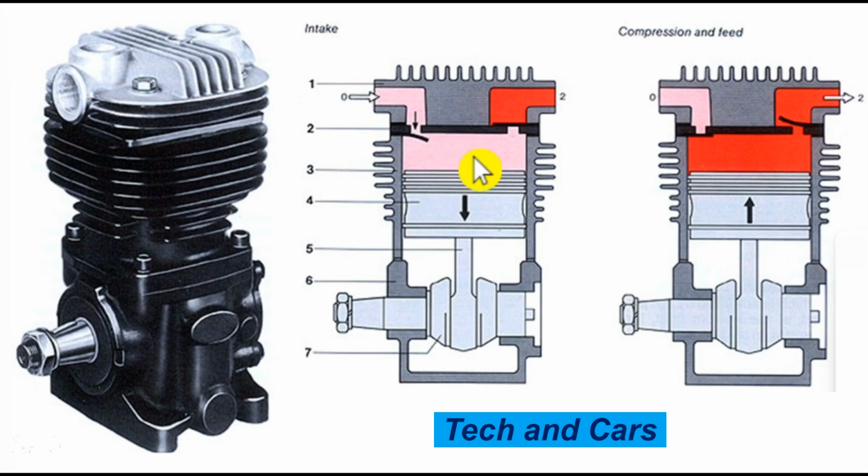When volume increases in this closed chamber as the piston moves away, a partial vacuum is generated and that will suck in air. Filtered air has to be supplied. Always make sure that the compressor has an air filter installed, or it should be directed from the main air filter of the car engine. Filtered air will be supplied to this cylinder.